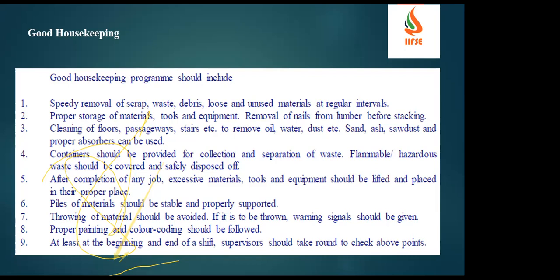And proper storage of materials, tools and equipment, and removal of nails from the lumber before stacking. They use nails for the shuttering work. Once they remove the shuttering, they have to take out the nails from the wood, otherwise there will be a chance of penetration and other injuries. And cleaning of floors, passageways and stairs to remove oil, water, dust, sand, ash and sawdust, and proper absorbers can be used. In case of any spillage, it must be collected and cleaned immediately.